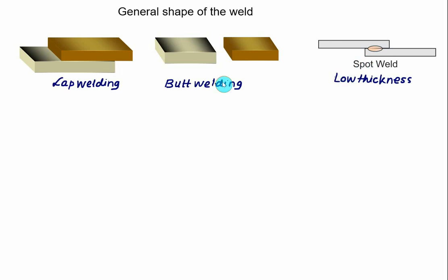As such, in arc welding, we do not require any type of force, only the fusion process is required. So here we are doing the welding, which is called a fillet weld. The shape is basically triangular, a cross section is triangular. The edge is called the leg size. This time we are doing the T joint, and we have a fillet shown here. We have plate 1 and plate 2. They are welded. It is also a type of fillet weld.